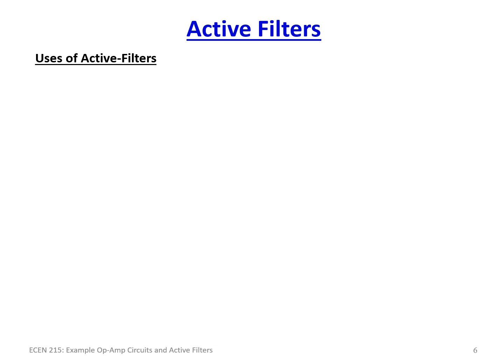All right, so now we're going to talk about active filters. We've been looking at all these different op amps, and we have had an introduction to frequency response, and we talked about two-port filters before where you have resistances and capacitances, and you can also do the same thing with inductors, for instance. But an active filter involves using one of these RC type filters in combination with operational amplifiers. And there are various reasons why you're going to want to do this. One of the things you probably have noted is that by using an RC circuit, if you do cascaded filters where you have filter 1, then filter 2, filter 3, filter 4, filter 5, it all depends upon those elements.